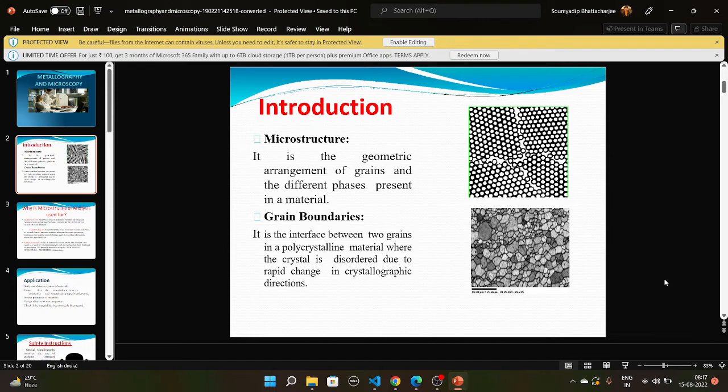So who can answer? Alpha iron. Have you heard of this alpha iron? Have you heard this term alpha iron, gamma iron, delta iron? This is called allotropy in iron, isn't it? So alpha iron plus a very small percent of carbon, that you please check, 0.05 or 0.005, probably 0.05 or 0.005% carbon will give you ferrite. Okay, gamma iron plus 2.1% carbon will give you gamma austenite.